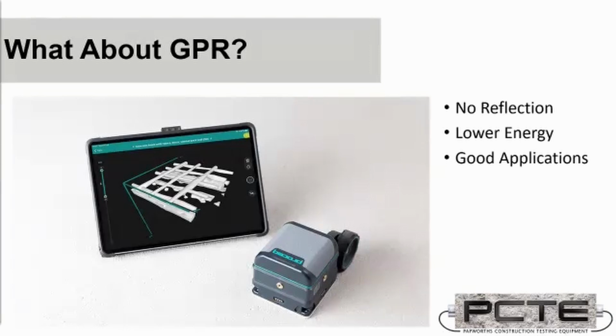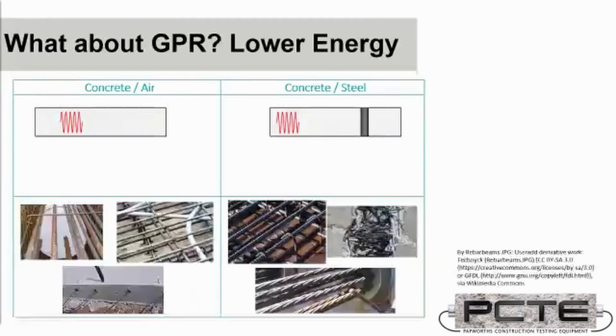Okay, I'll keep moving, but that's a good starting point, just where you need more information, where it's not as straightforward as locating an embedded reinforcing bar, post-tensioning, or even something like a slab thickness. We've also got Mark saying that reinforcing may hide voids below, and it's quite right. Essentially, radar is most sensitive to steel.